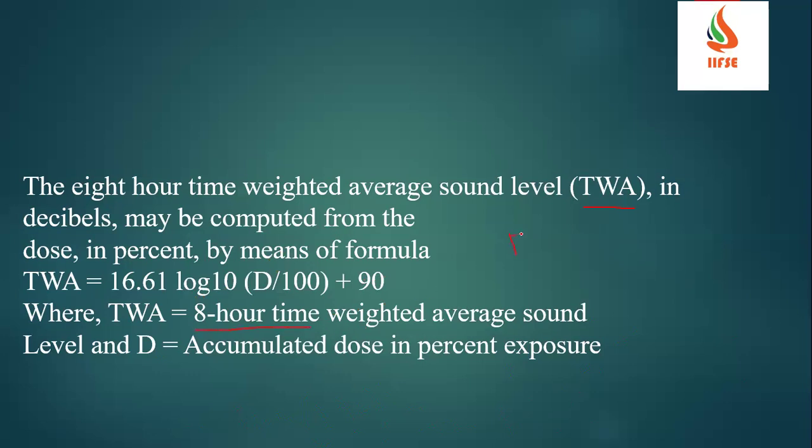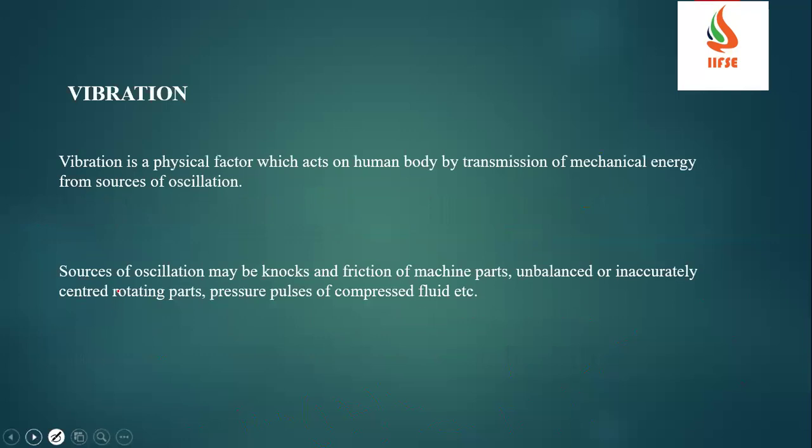Once you calculate the noise dose D value, you can calculate the time weighted average, which means what is the maximum allowable per day. For 8 hours, what is the maximum you can be exposed to? This you can use in your practical experience calculations. Now we'll see vibration.